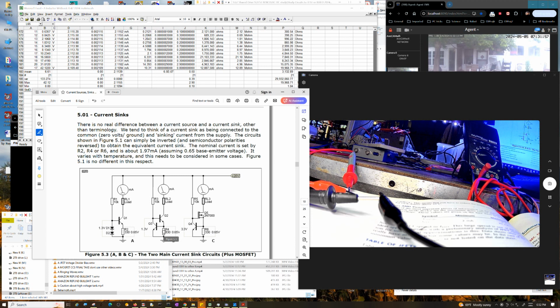So instead of it being like 0.7 volts, let's say it was at 0.8 volts, well, it's going to decrease that voltage on its collector in order to starve current from this transistor, so that it reduces the voltage drop across the resistor. That's how it works. It's a very simple principle, but in effect it ends up controlling the current through this too.